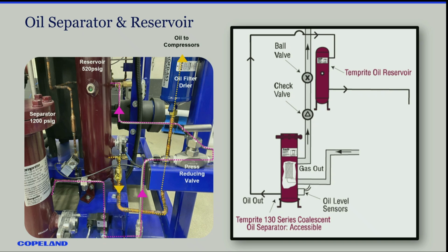And one thing about CO2, just refrigerants and oil: when there's moisture in them, moisture always tries to find an equilibrium between refrigerant and oil. So there's going to be a percentage of moisture traveling with that refrigerant. So drying it here and filtering it is super efficient. It's good for our compressors, so that's why, of course, we promote that.